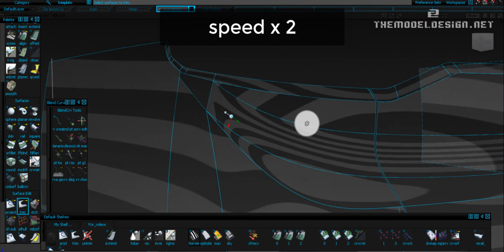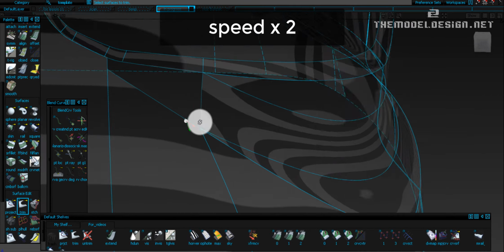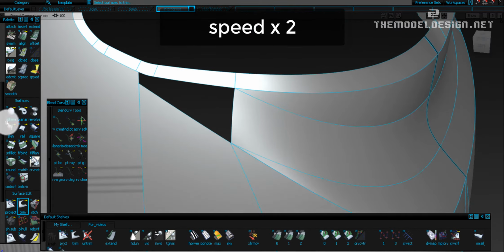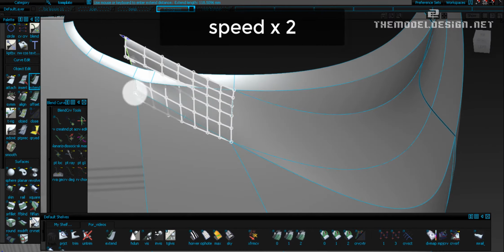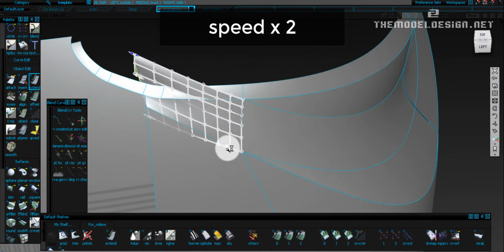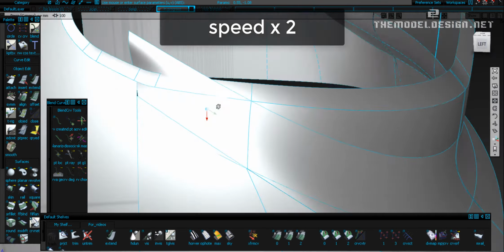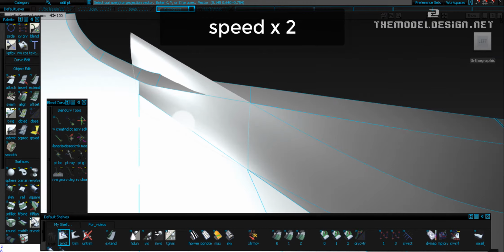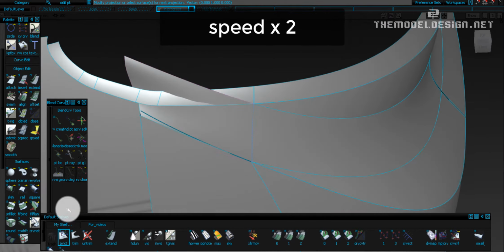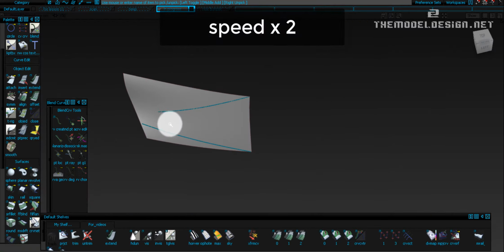Let's examine the geometry with zebra stripes. I think the zebra stripes look good at the moment. We can try the old trick and extend the left edge with a merge option off. At the moment for you it might look like I just tumbled the view around, but in fact over the years I developed some habits of working. I just moved the view about to give myself more time for figuring out the next step.